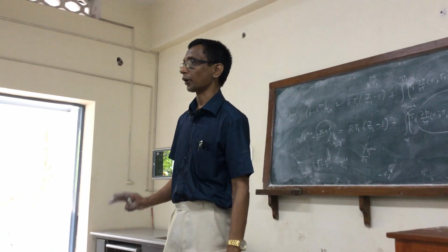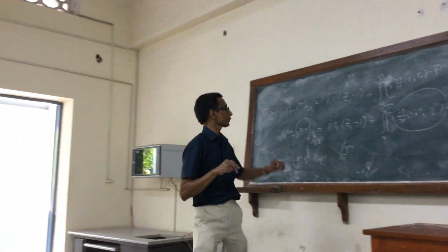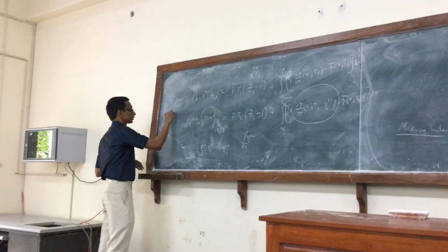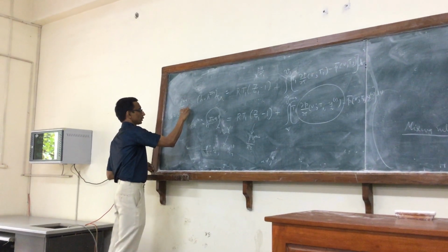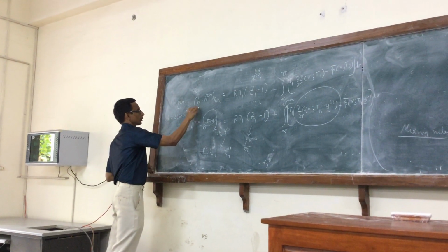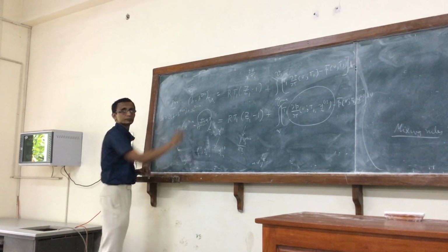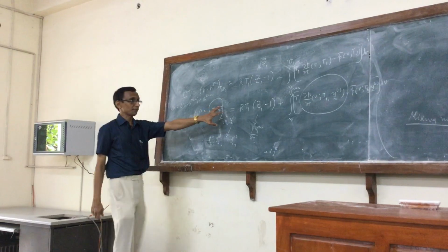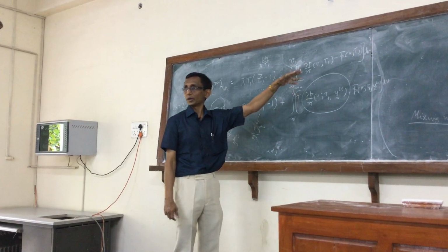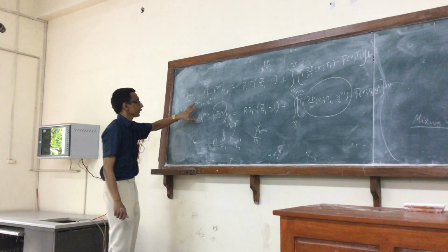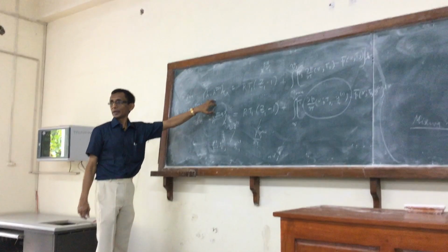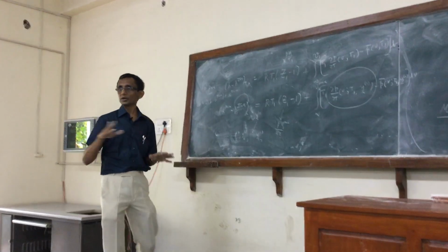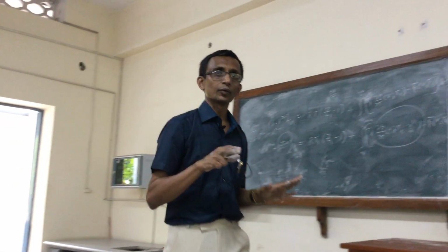So we take up these points. First is what are the properties of the ideal gas mixture. So what we will do is, if I want to calculate for instance delta H, I will do the same trick. That's all. So this I know how to calculate from the equation of state for the mixture. Obviously we have to go and find the volume by solving the cubic equation of state. And for this I need to know the properties of the ideal gas mixture, which can be related to specific heats and so on. So the procedure for the mixtures is identical to that of the pure component.